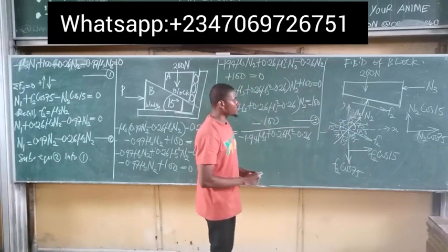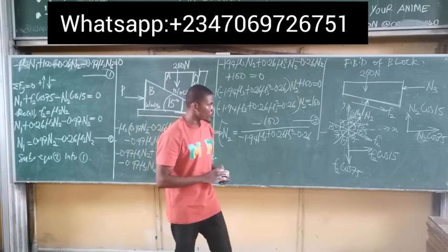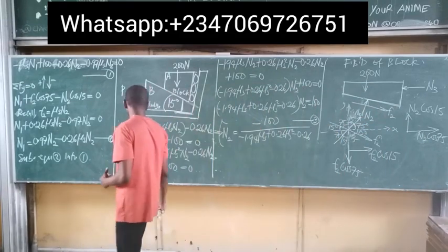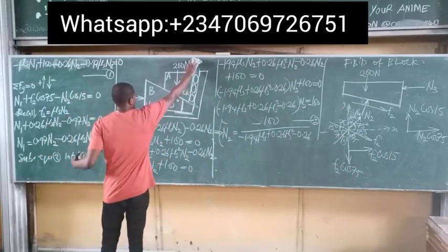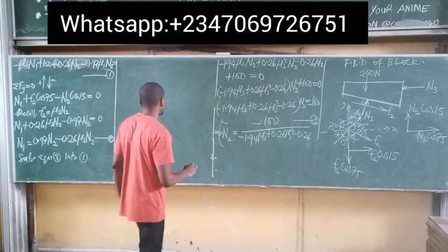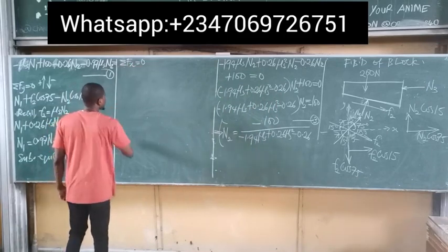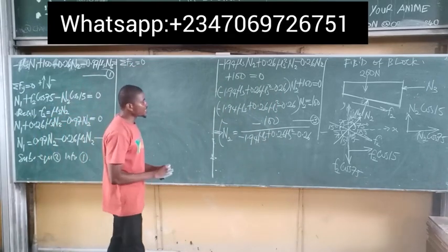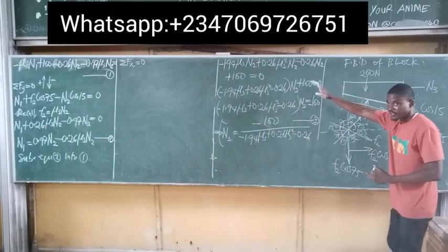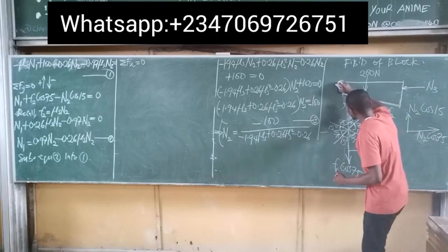That's all. This becomes the analysis of the wedge of the block. So we simply apply the equation to it. Okay, so I think I can write here now. Alright, so we apply the equation summation of Fx is equal to 0. And remember, the motion of this block is simply what? Up the plane, not forgetting. The motion of the block is up the incline. And remember, up the incline is simply like this, up the plane.